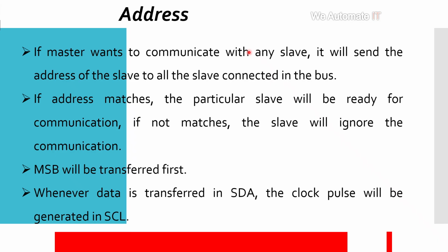Okay, so the MSB will be transferred first. MSB means the most significant bit, which is transferred first in the address. Then, whether the data is transferred on SDA, the clocks will be generated on SCL.